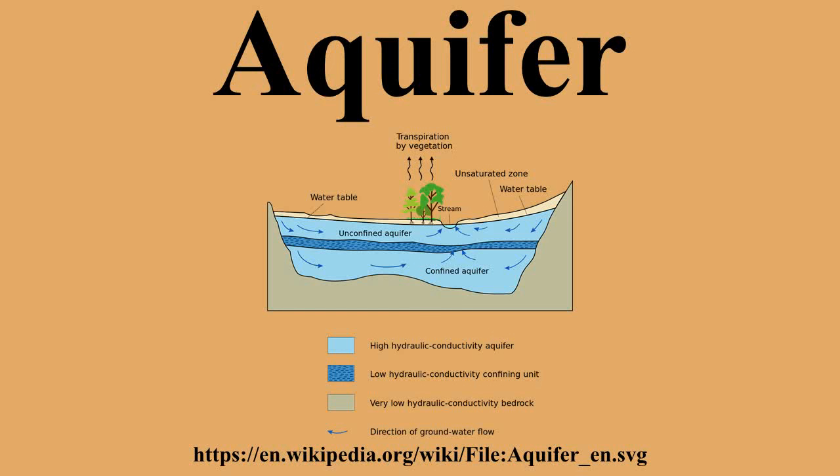Aquifers that provide sustainable fresh groundwater to urban areas and for agricultural irrigation are typically close to the ground surface and have some recharge by fresh water. This recharge is typically from rivers or meteoric water that percolates into the aquifer through overlying unsaturated materials.